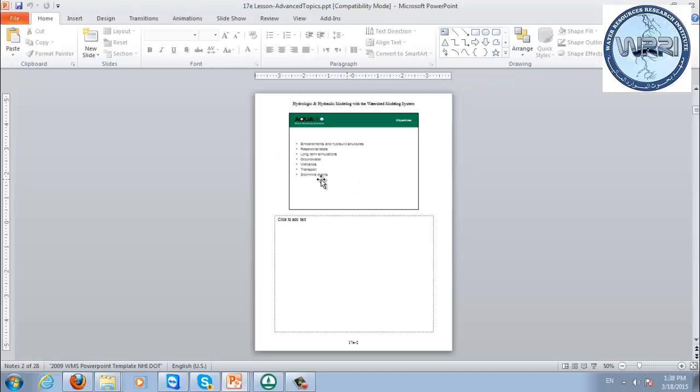So, is anybody interested in doing storm and tile drains with GSSHA? Or storm drains? You know about tile drains? You know what a tile drain is? So they're used in farming usually, and they're used to drain soil. So it's an underground pipe with perforations in the pipe that's used to keep the soil from being too swampy. That's a tile drain. And so the groundwater goes into the pipe and drains out the pipe. Do you have tile drains?